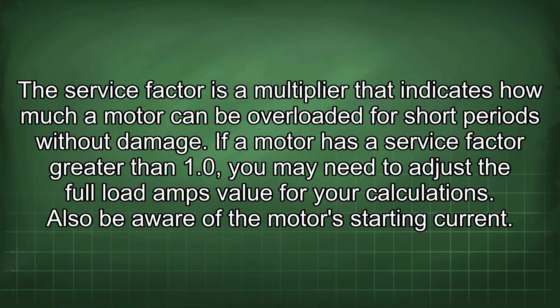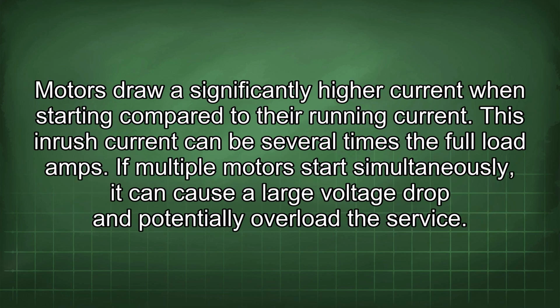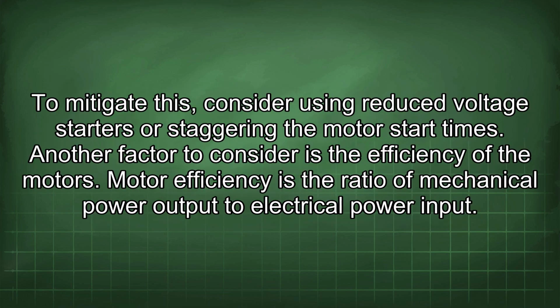Also be aware of the motor's starting current. Motors draw a significantly higher current when starting compared to their running current. This inrush current can be several times the full load amps. If multiple motors start simultaneously, it can cause a large voltage drop and potentially overload the service. To mitigate this, consider using reduced voltage starters or staggering the motor start times.